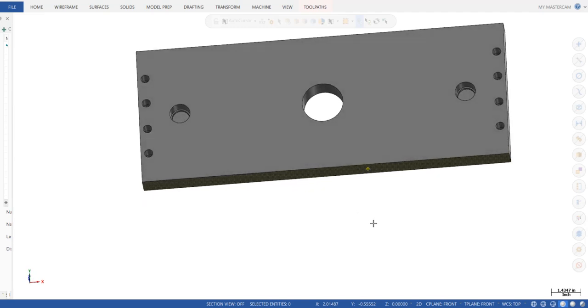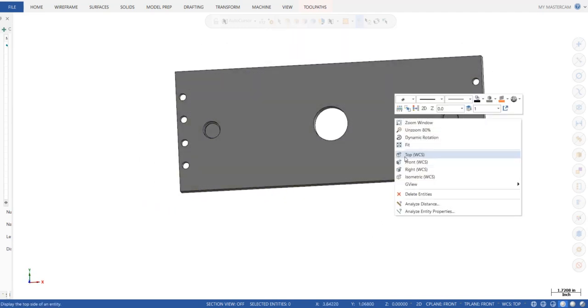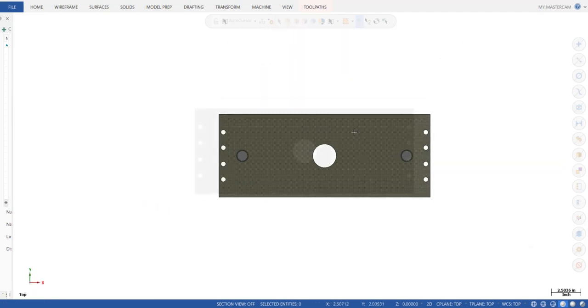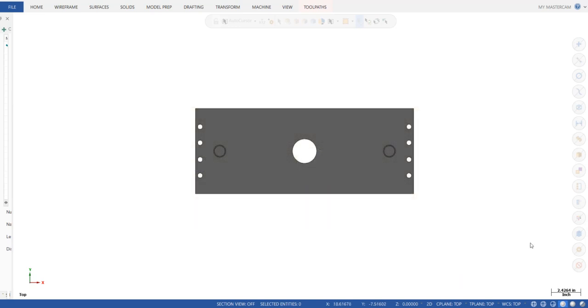Okay, so here we're back to top. Alright, so I hope that makes sense. So what I'd like you to do is at work, when you're making parts, grab one of those parts, take a look at the print, and study how these projections are. Top view, front, back, right, left, and if there's any other section views. And if you can see the 3D on the print, just like you see the 3D representation of your part.